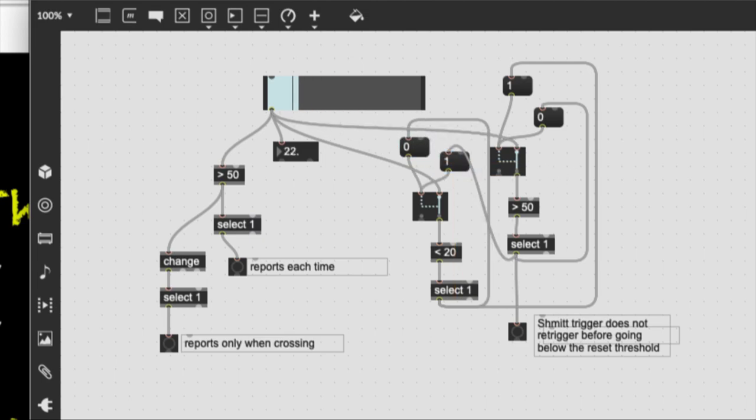Okay, so let's look at this happen. This is now ready to accept the trigger. The trigger happens, and you see both switches have made a switch. So once this has happened, I'm insensitive to further triggers, and at this stage, I am actually looking for a reset. So this one, you see, has sent a 1 to this switch, making it switch right, and 0 to this switch, making it switch left.